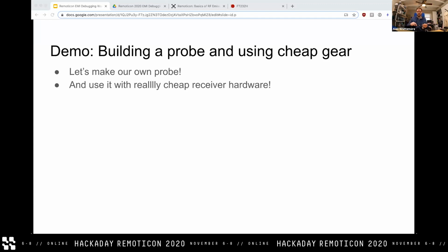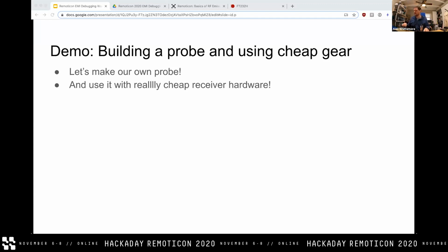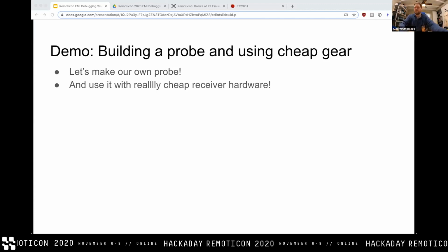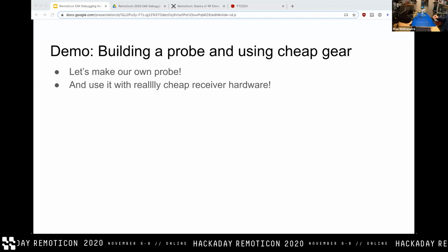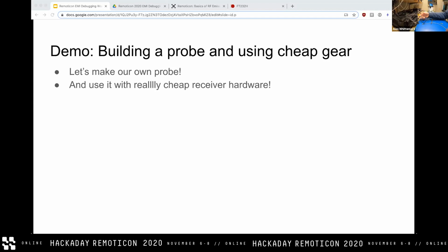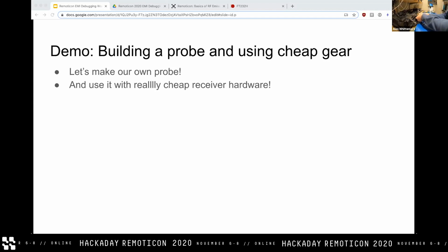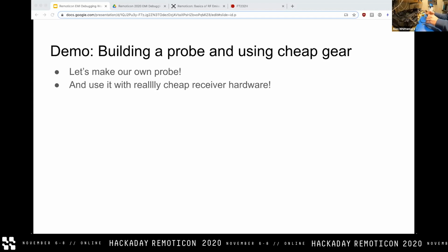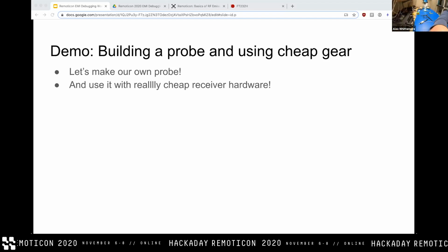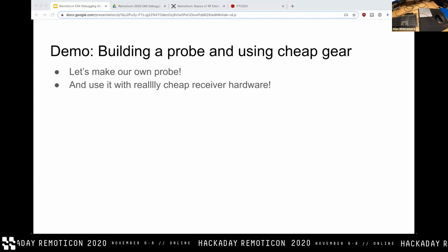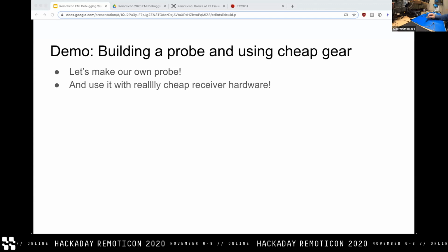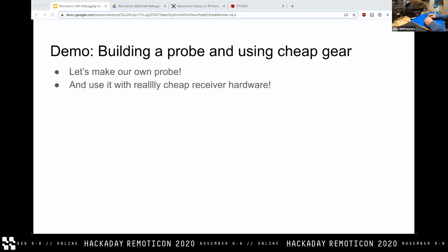I got this guy, the one that I recommended all of you buy. I have to plug it in over here because USBs are at a premium. And then I will go over here, pull my LNA off here. This is a critical aspect that I didn't cover. I covered this in the instructions, but the way we'll be powering this particular LNA is via a bias T.